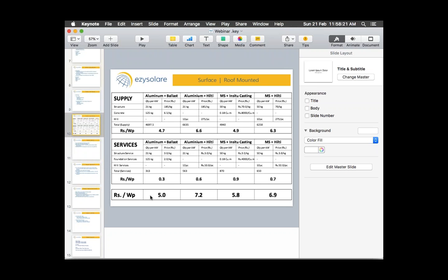Double axis, basically the kind of structural components used are pretty similar to the single axis tracker. The same kind of material, same kind of torque tubes are there. But I'd like to share a new design introduced by one of the vendors in the Indian market. Double axis versus single axis is a good question. First we have to understand why you want to put double axis. Let's say you are sitting somewhere in Tamil Nadu, at a low latitude. In that case, double axis won't fetch you very good incremental generation numbers over single axis.